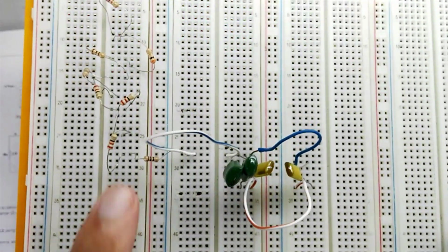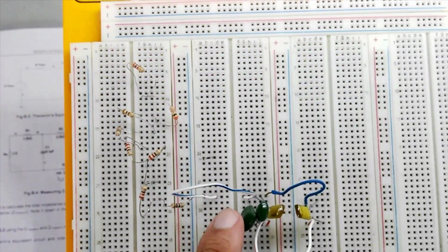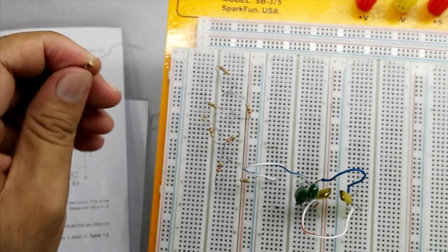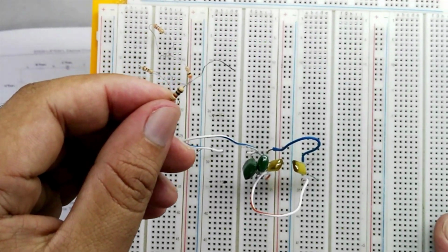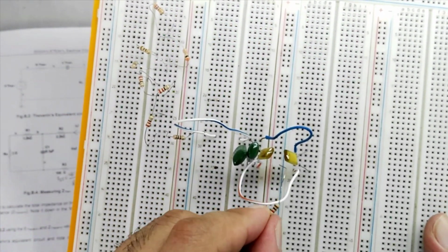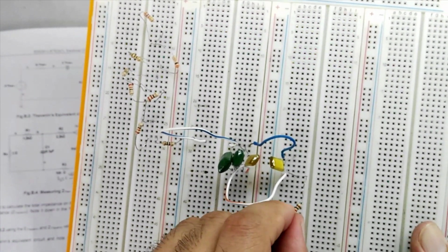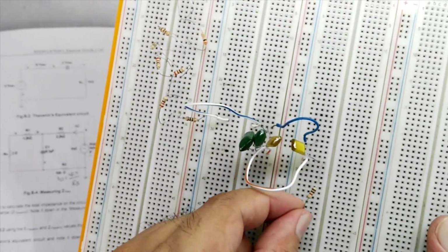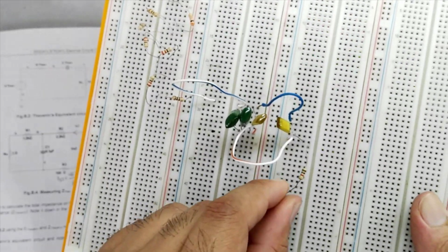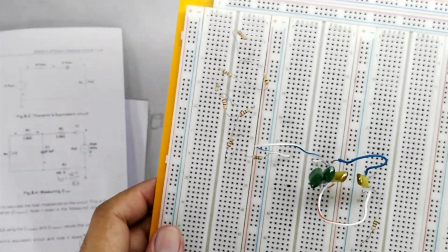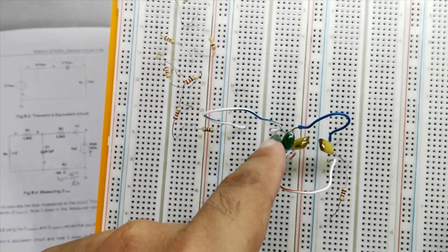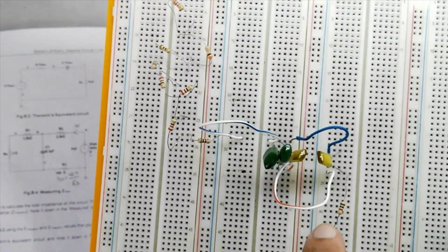So I use a wire to connect this in series. Now I'll need to place the load of 1K which we removed earlier and place it in series with this capacitance, which we'll do by placing the resistance here and here. So we have completed our circuit. This is the Thevenin equivalent resistance, Thevenin equivalent capacitance, and this is the load.